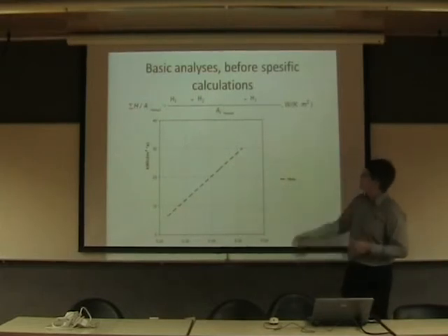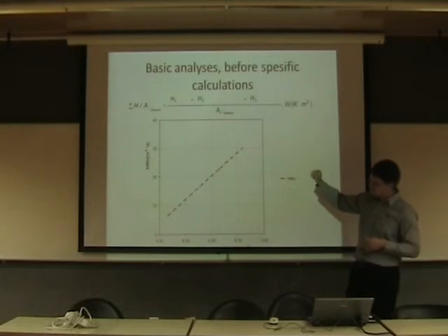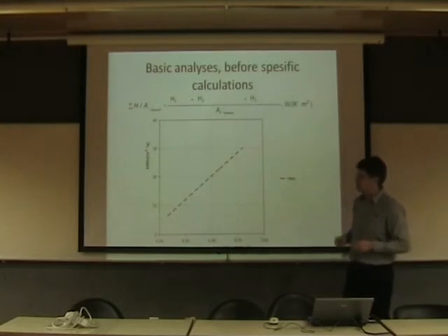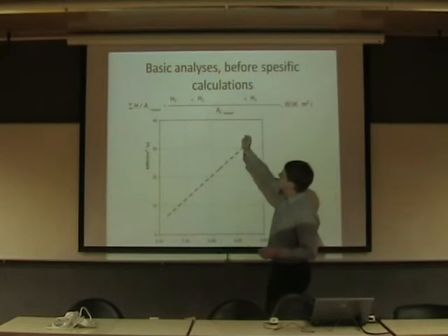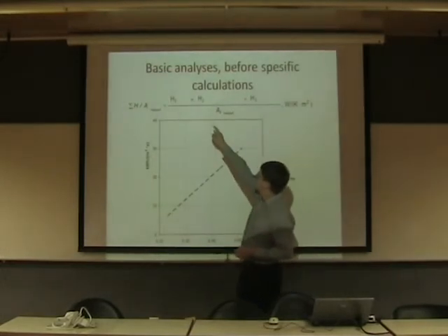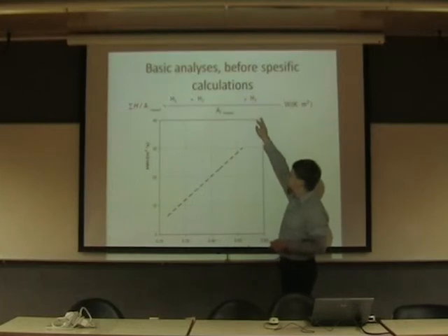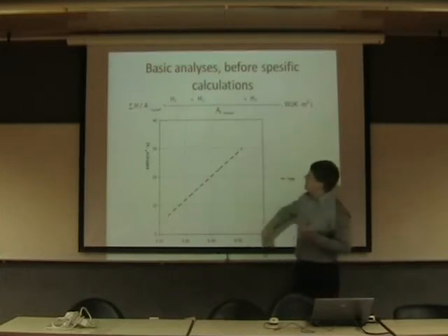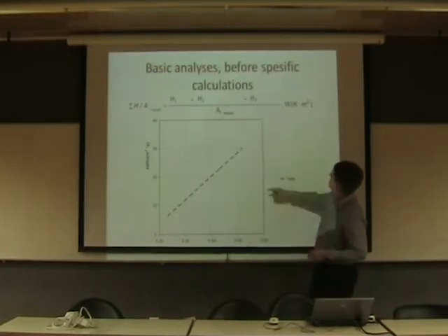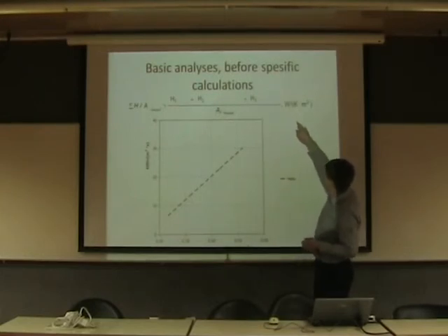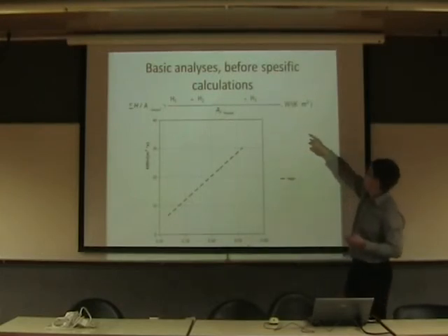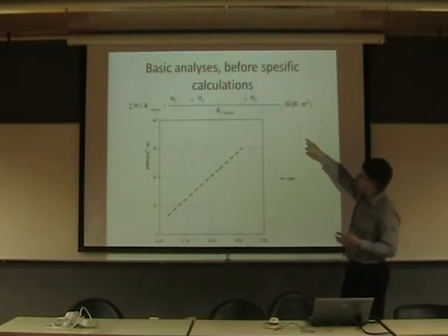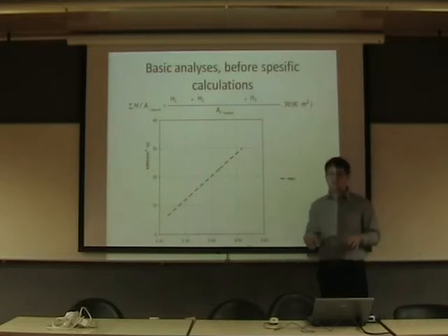When we take the specific energy losses from envelopes, thermal bridges and infiltration and compare them with the heated area, we get a number showing how many watts we lose per heated area when the temperature difference is 1 Kelvin.